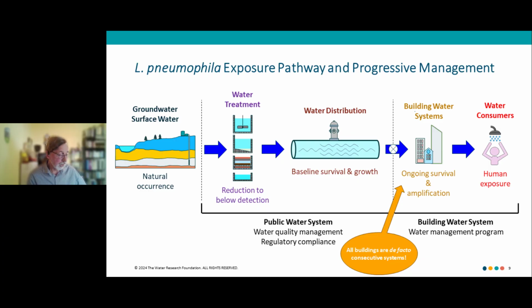And these pathogens are different from the ones that we're more accustomed to dealing with because they're inhalation risks. They're a problem because they pose a latent risk. What does that mean? It means that they're present at some kind of a baseline level, both in the water distribution system and building systems, and they're just waiting for the conditions to become right to amplify.